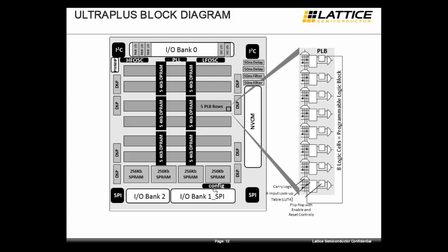And there is a configuration memory, a non-volatile configuration memory available in the device called NVCM. This is a one-time programmable configuration memory where if programmed, it is not a reversible or reprogrammable function. So you should always make sure that your code is 100% before programming the NVCM. Otherwise, the function of that memory becomes unusable.